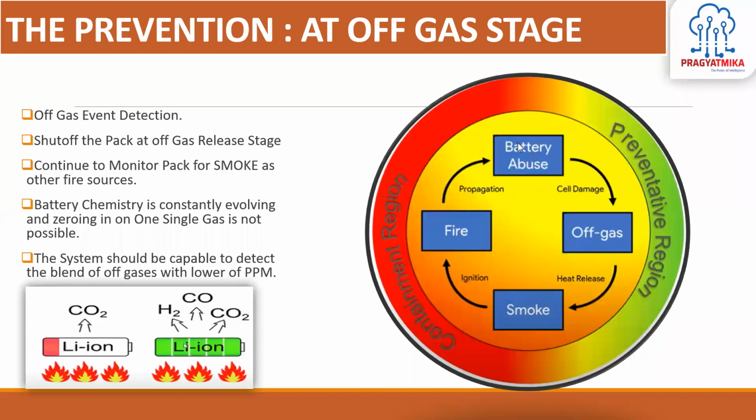But if more bulging of gases is happening inside the pack, it will definitely explode the cell capping and the battery pack casing. So this is what we need to do. Thereafter, once you have cut off the load, a fire could still have started. So we also monitor the smoke.